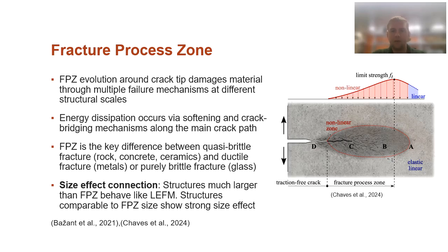We saw the fracture process zone in the last diagram, but here we see it again in a zoomed in version on some concrete, where you can see those micro cracks existing at a region away, and they get progressively harder to see as you get away from that crack tip because they're encountering less stress, but it's effectively working to dissipate and soften this stress at some point away from the crack tip.